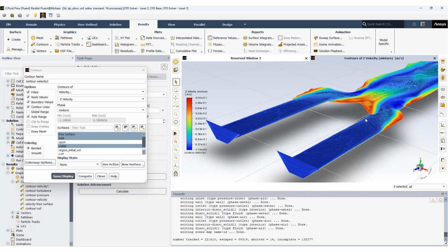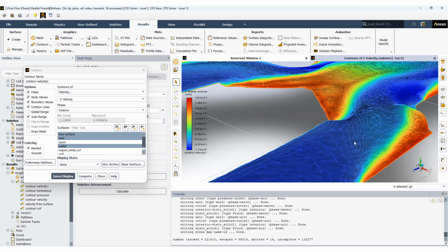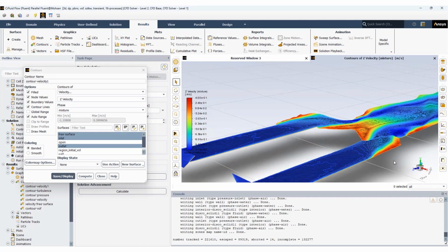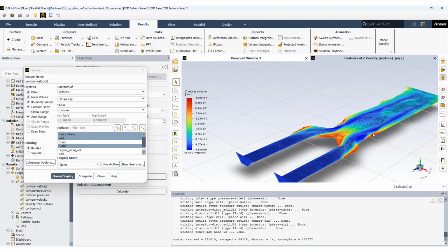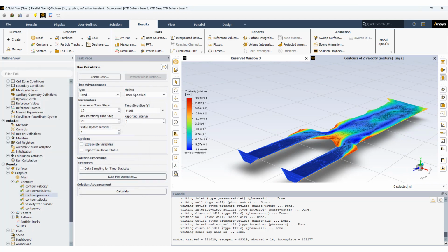As you can see, here we have positive velocity, which means it is moving backward, and here exactly what we see is recirculation. And at these edges, which are plotted at the free surface, also the positive velocity for the z component, these are the waves traveling, moving backward on the sides of the trapezoid. This is one way of illustrating what's going on for the velocity.